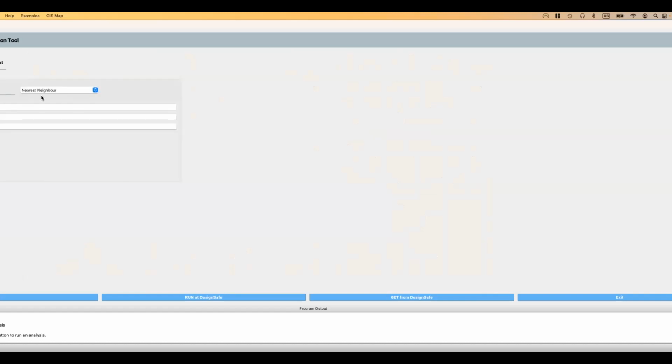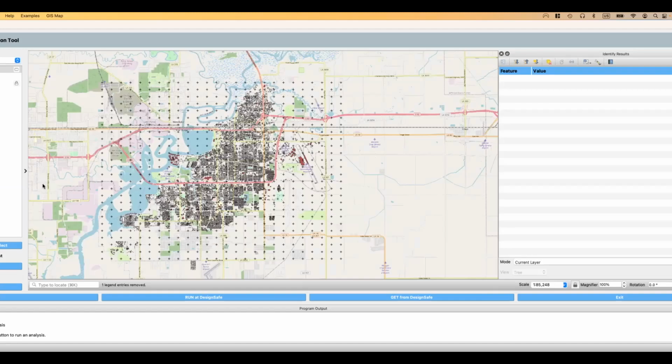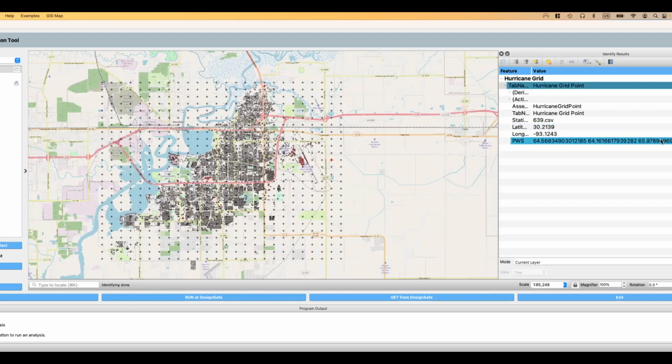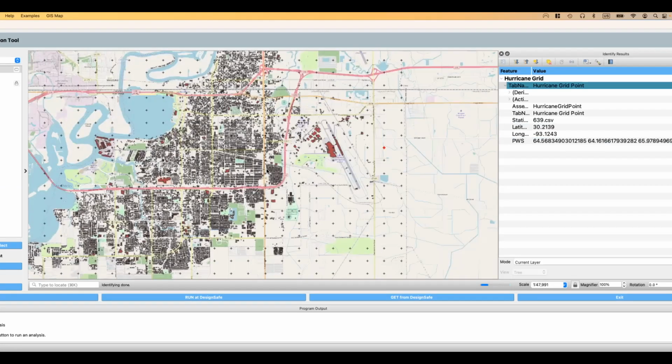And I can go here now and you'll see it's nearest neighbor, which allows me to sample a number of neighbors randomly and take how many samples from those neighbors. So remember before I had a list of intensity measures at each point. If I click here, you'll see there are 3 wind speeds, and it'll just go around your neighbors sampling these different wind speeds to get some statistical idea of your intensity measure using the nearest neighbor approach.